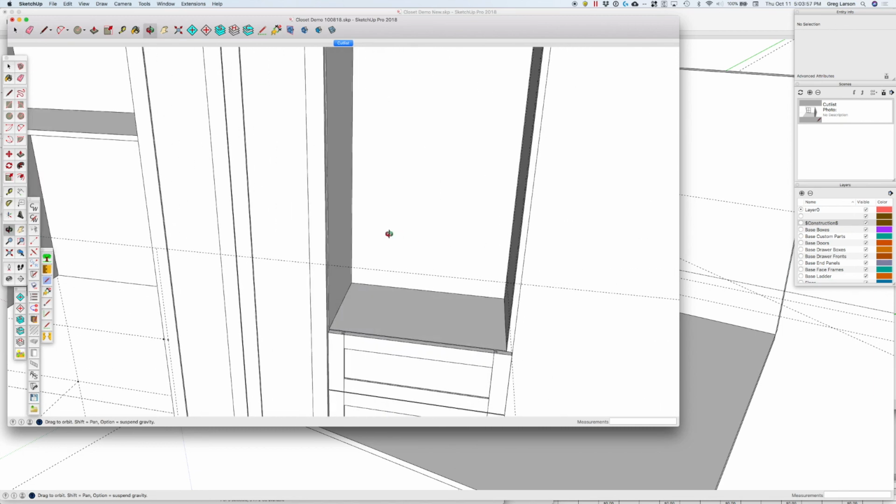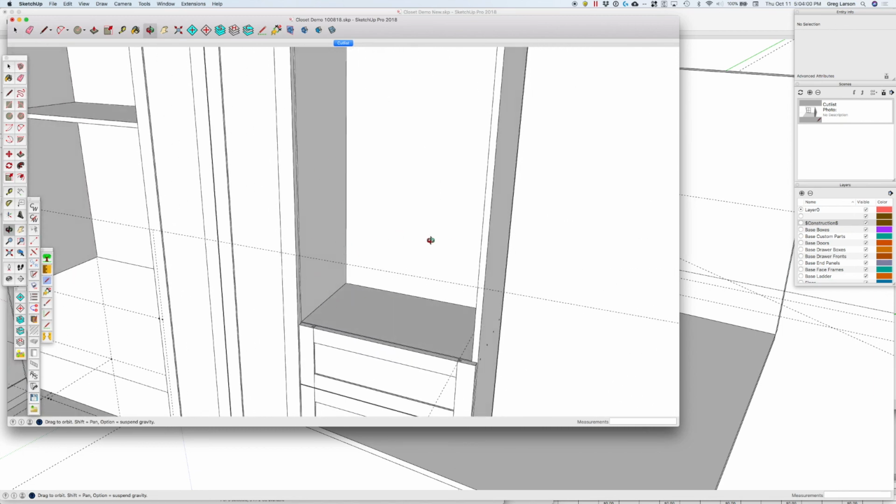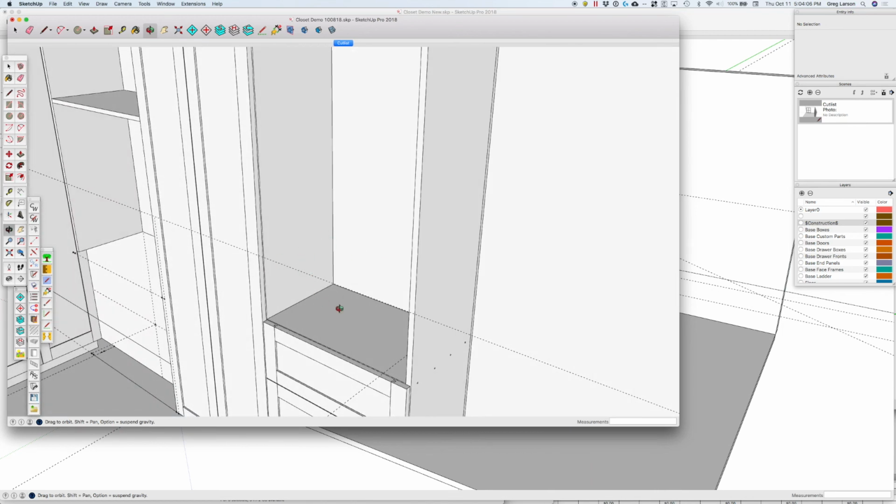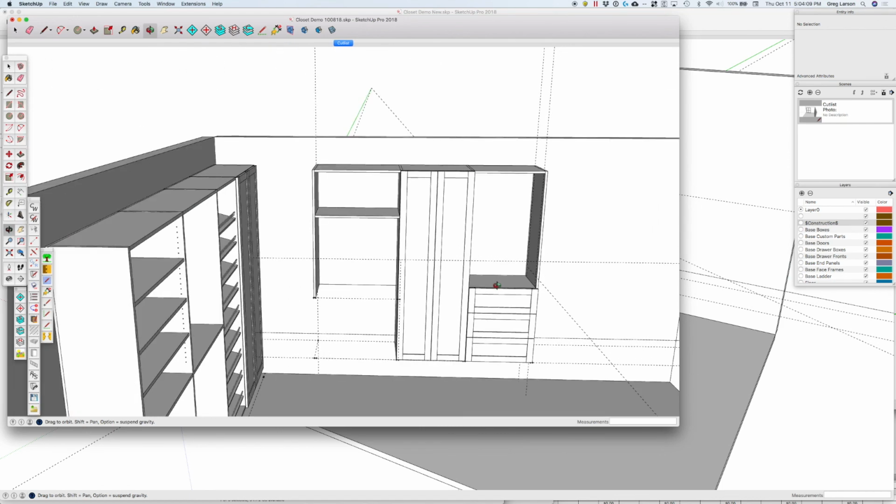And then I could go over the other side and do the exact same thing. Or I could do the trick with moving the holes over. In this case, it'd probably be easier just to go replicate it on the other side. So you can just keep going and going. Basically, the basic concepts are you're overlapping your cabinets and deleting a side, selectively drilling holes where you need to, using the line boring, or you can go into CNC mode and use that to drill your holes for hinge plates and drawer slides when you insert drawers in there.